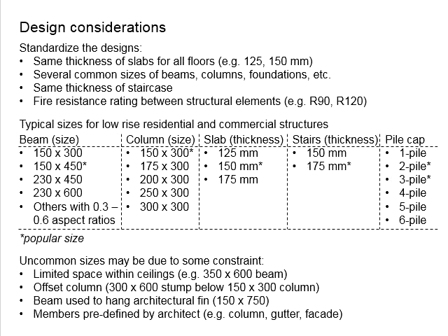Normally, we will try to avoid a ratio of more than 0.6, unless we have a problem with the maximum allowable depth of the beam, as restrained by the ceilings or certain required headroom. In order to make the member pass, we have no choice but to increase the size of the beam by width. This is definitely going to be uneconomical, as you will see a large amount of reinforcement bar to be embedded in this section.